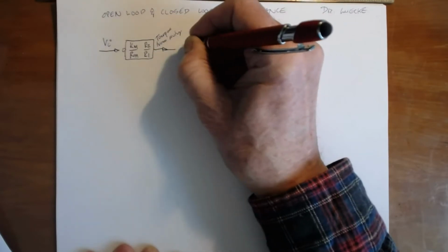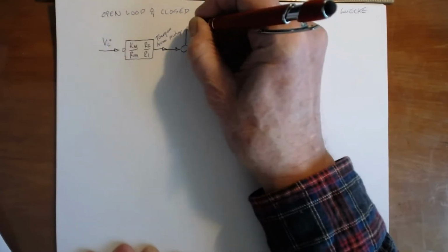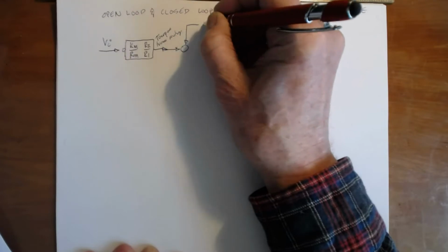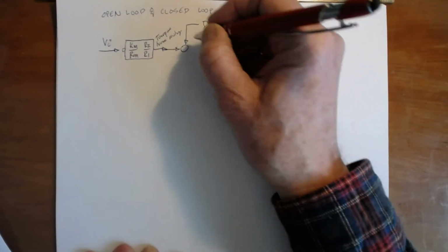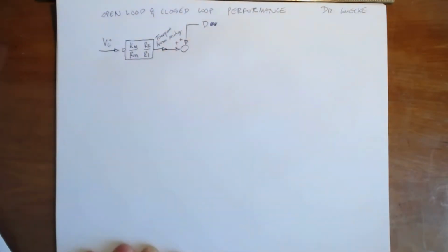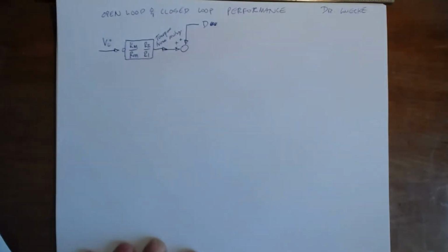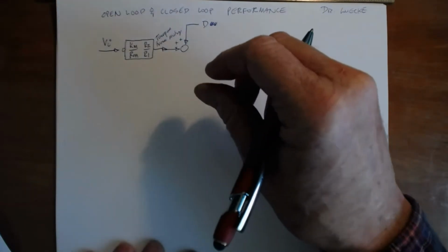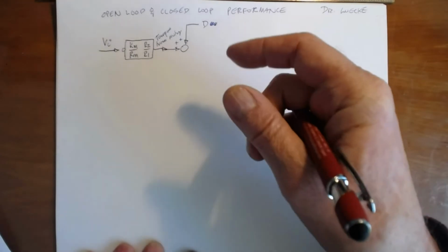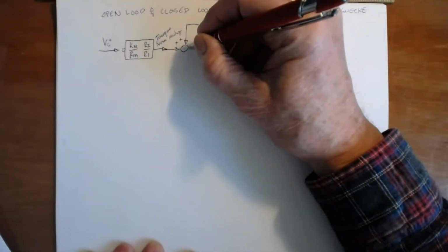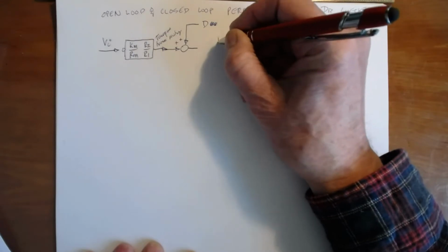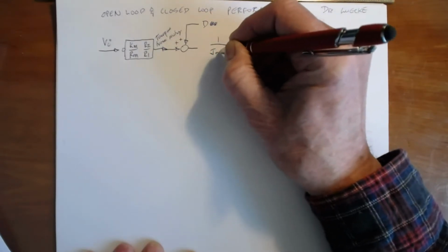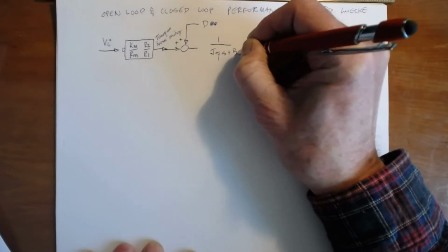Now, the torque on the motor gets applied to the shaft, and what I've been doing is also saying that there's a disturbance force on the output of this thing. So I'm going to put a plus and a plus, a disturbance force on the output of the motor shaft. That may be something that you grab a hold of the motor shaft and just turn it. That's fine. Now, the dynamic parts of the motor we've developed look like this. 1 over J equivalent S plus B equivalent.